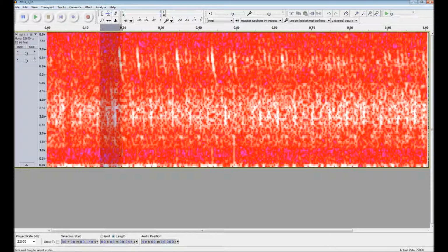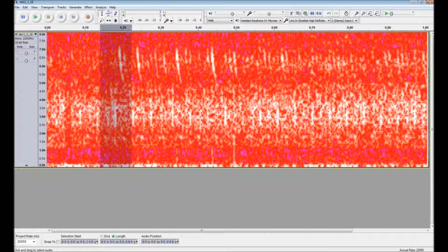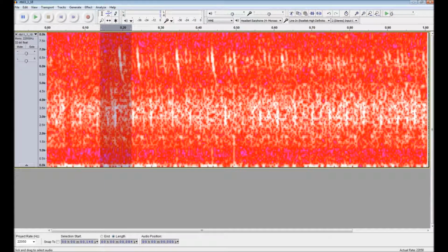We are in this spectrum. This is the noise level of the ECU, and this is what causes phantom knock. This one. I am triggering real knock events with a signal that's equally strong to this drivetrain noise, if you will. I am triggering real knock events with a signal that is equally weak. And here we have a real knock sound.